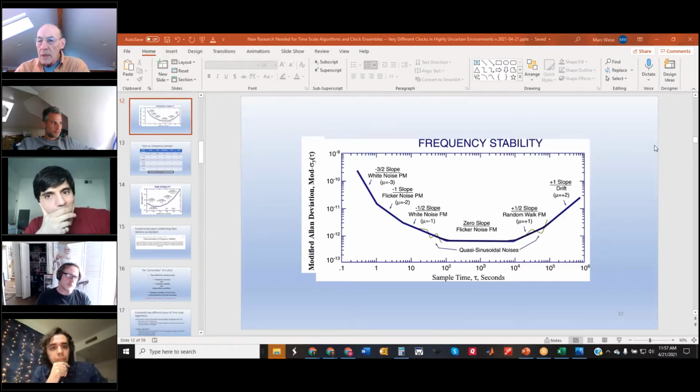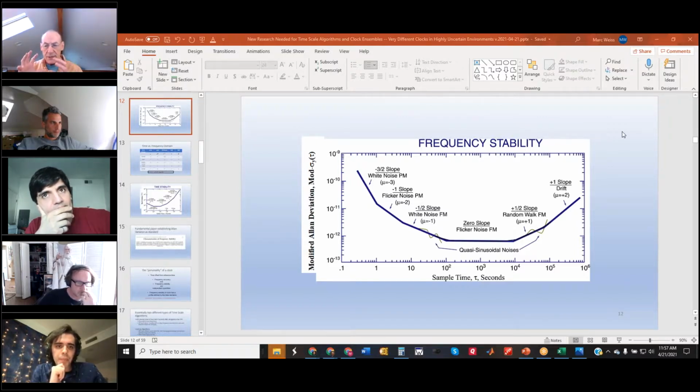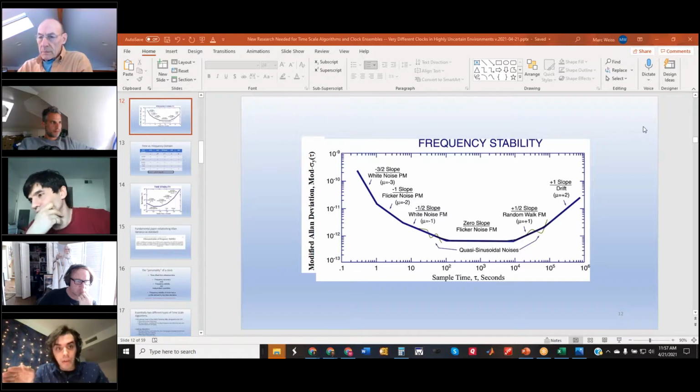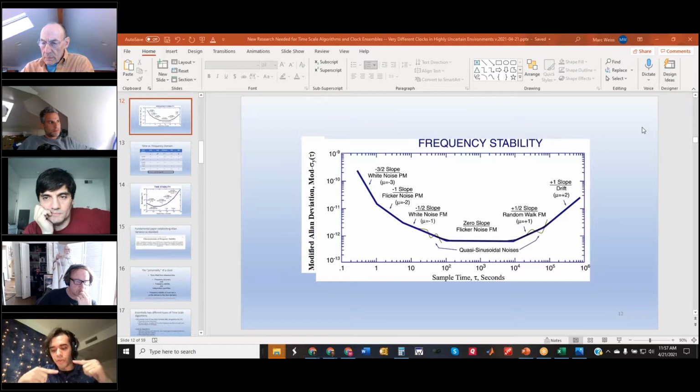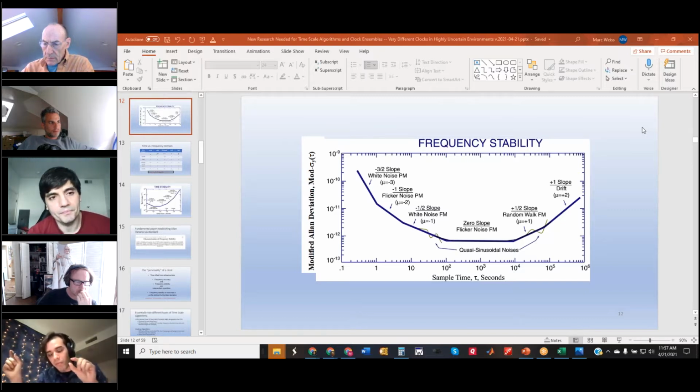So one of the things I'm hearing is that you're talking about steered clocks. Are you talking about a synchronization algorithm where all the clocks are trying to be steered to one rate and one time? Well, sort of both: everything being steered to one rate, and the short-term clock being adjusted by the more accurate long-term clock, and steering that much finer clock along, and then you can trust the smaller clock.